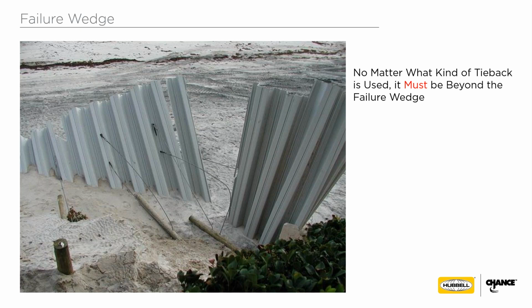So here you can see a little small vinyl wall. Not that there's anything wrong with vinyl sheets. They used little small 4-inch drag piles that were only like 4 feet long. Couldn't have much lateral capacity to begin with, on a cable that must be 5 or 6 feet long. So it's just right behind the wall. So the wall's just not even intended to survive a big storm. It's just a Band-Aid.